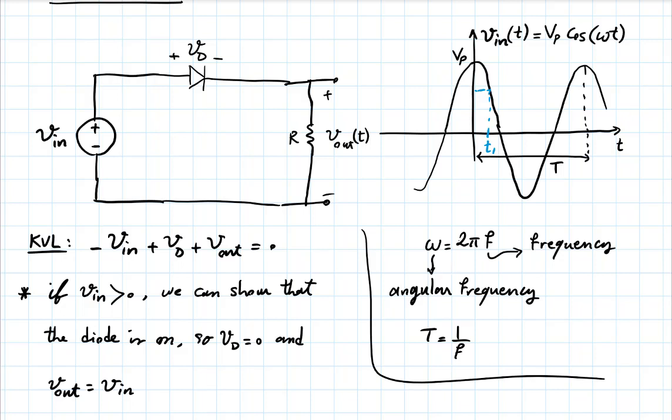Let's assume it's on. So if my input is minus 3 volts, and the diode is on, which means there is a current going from left to right, I have a minus 3 volt rise here. I have 0 volts there. And then I have a current going down in the resistor, which means a positive voltage on the resistor.